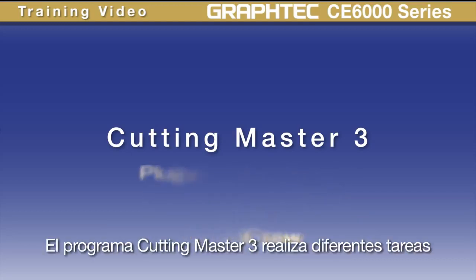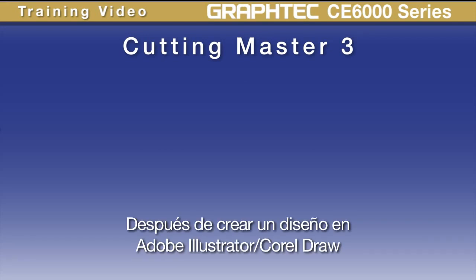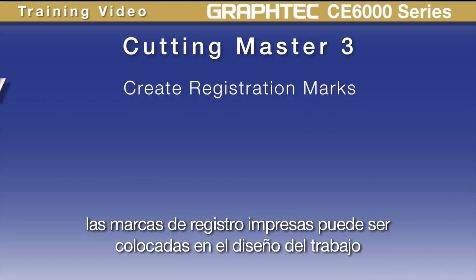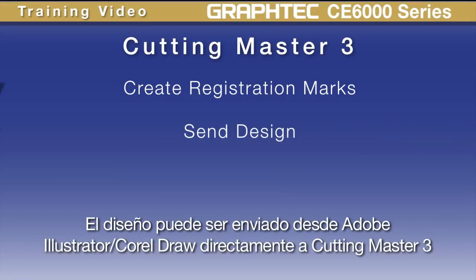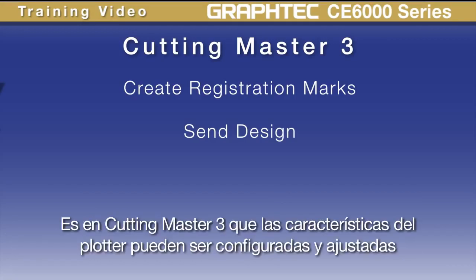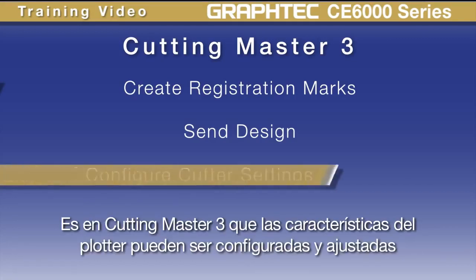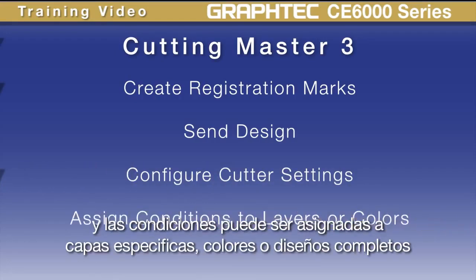The Cutting Master 3 application does several tasks. After creating a design in Adobe Illustrator or Corel Draw, registration marks for the print and cut process can be placed on the job design. The design can be sent from Adobe Illustrator or Corel Draw directly to the Cutting Master 3 application through the special GraphTech plugin that is added to Adobe Illustrator and Corel Draw. It is in Cutting Master 3 that cutter settings can be configured and adjusted, and conditions can be assigned to specific layers, colors, or whole job designs.